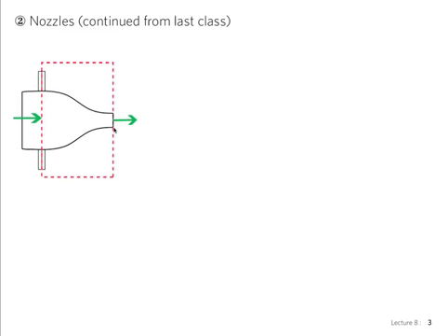So I know that at this point there's a free jet. The word free should tell you that it's just at atmospheric conditions. So I can know that this is atmospheric pressure here. If I'm going to call my section 1 and section 2, I know that the pressure at section 2 is atmospheric. The pressure at section 1 was given, I believe, yes.